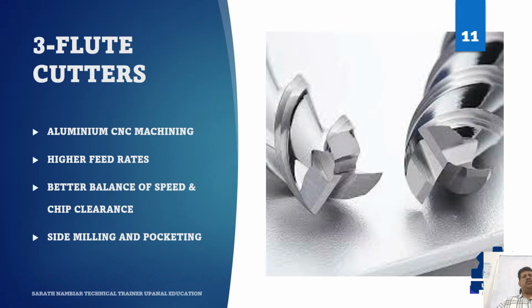Can it replace two flute always? No. If deep slotting with chip packing risk exists, two flutes may still be better. But for many CNC VMC aluminum jobs, three flute is the excellent modern choice.